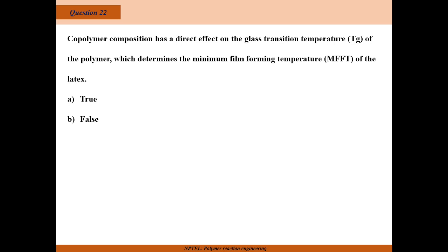Actually, here we are looking at film forming capability, because not all materials can form a film. We also have some copolymer with polyamic acid, which gets converted into polyimide. That is called Kapton film, right? The indigenous equivalent of that Kapton that we make has polyamic acid as a resin, which starts from anhydride, BTDA, with an amine. So both together form this polyamic acid.